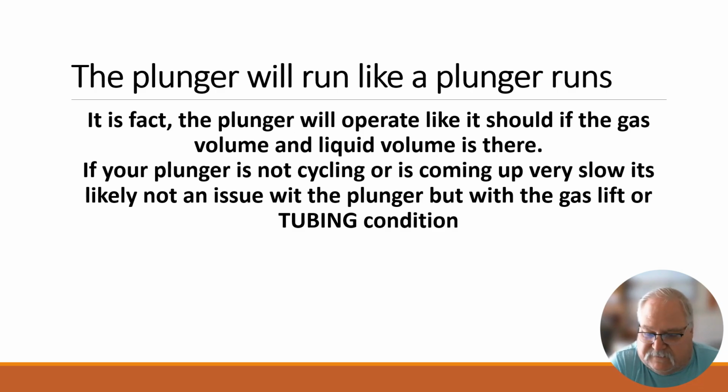So again, if you've got 500,000 and you're lifting 20 barrels of fluid, the plunger's coming up, right? You know it would work if it was a regular plunger lift well. If it's not working properly, or you're having to inject 1,000,000 cubic feet of gas or 28 E3 into a well to get this plunger to come up, there's a problem. It's not the plunger, it's where the gas is going.